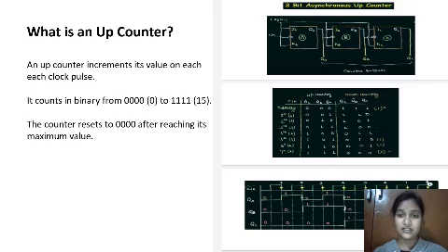Here you can see the state diagram and state table. Initially we have QC, QB, QA all zeros. The down counter will be opposite to the up counter, that is 1 1 1. The first down counter value will be 0 0 1 and the opposite of this will be the down counter. So all these values are the same. If you see the waveform for this up counter, first the clock pulse will be 0 1 2 3 and this clock pulse will be taken from the table.